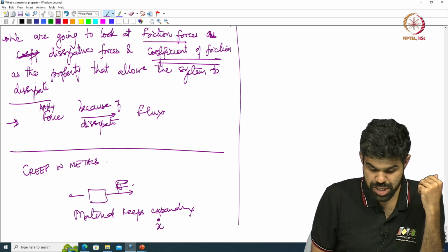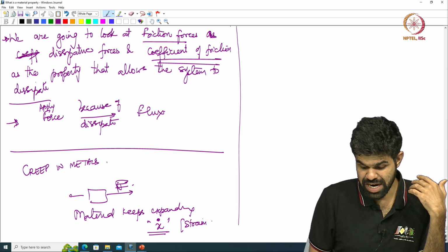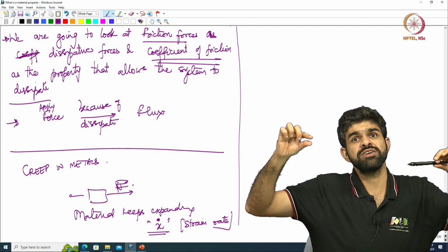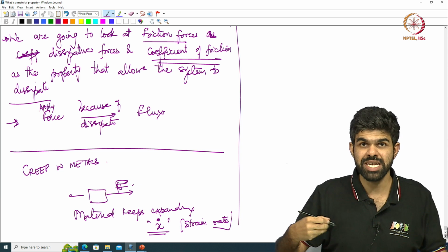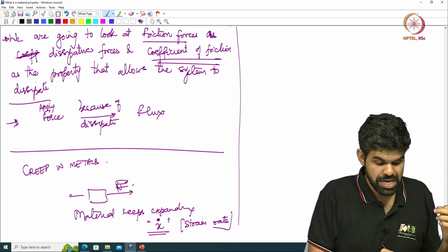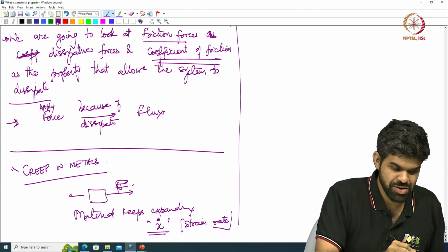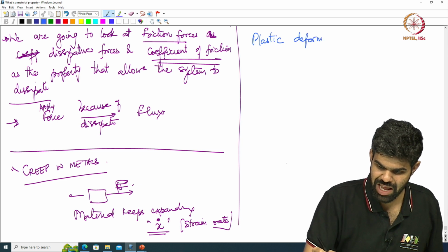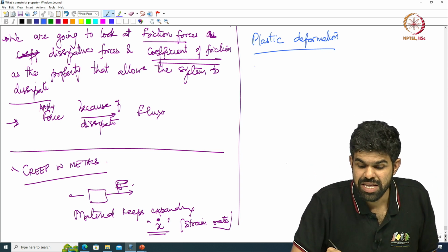Or in other words there is some x dot. So, I create some sort of a strain rate in the material. By applying force, if I am just stretching the material forever and ever without really changing the magnitude of the force, that phenomenon in metallurgical engineering, or in mechanics, is called creep. So, the material is creeping. Now, creep is what is called plastic deformation, not elastic deformation. It does not store mechanical energy, rather, no storage of mechanical energy, it is not a Hookean spring anymore.